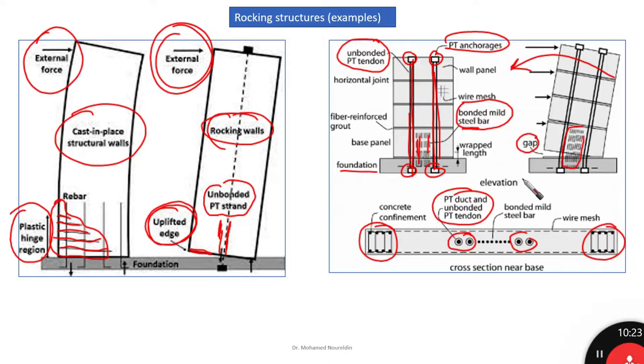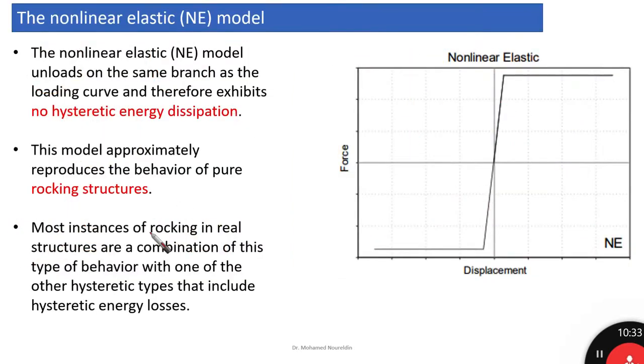They might work for energy dissipation, but actually in most common cases we are putting some anchorage, or some rocking technique or recentering technique, and we provide with it some kind of energy dissipating elements like steel reinforcement bars or dowels or something.